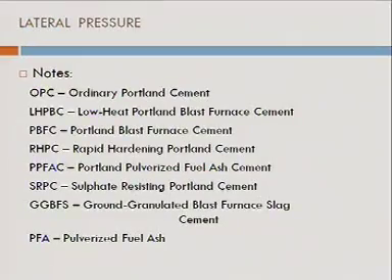So, now you remember that C1 is dependent on the shape and size of your form, whereas C2 is dependent on the constituent material for concrete. So, depending on what blend you have used, depending on what cement you have used, the values change from 0.3 to 0.6, whereas C1 varies from 1 to 1.5 depending on whether you are doing it for wall pressure computation or whether you are trying to calculate the column pressure computation.